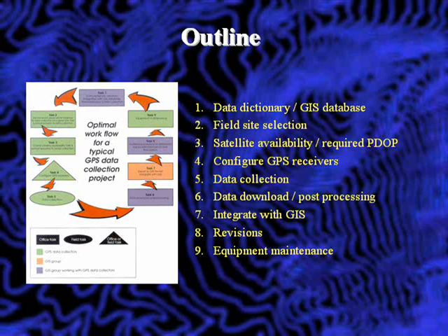And there are other things that we noticed. For example, for differential correction, you cannot go over the weekend. So always use a file. That's why I always tell you back up often, especially at the end of the week. Use that file, then you can differentially correct it. It won't allow you to collect on the next Monday.